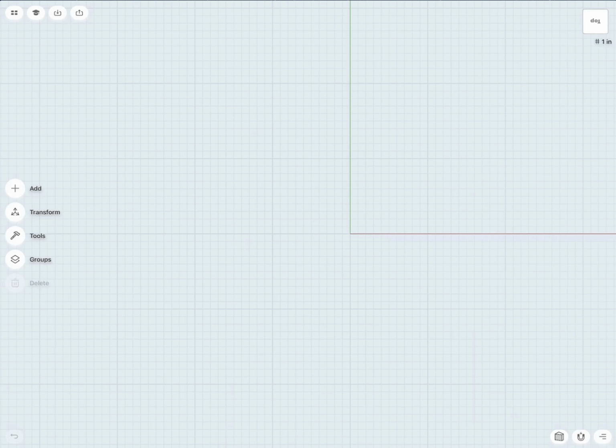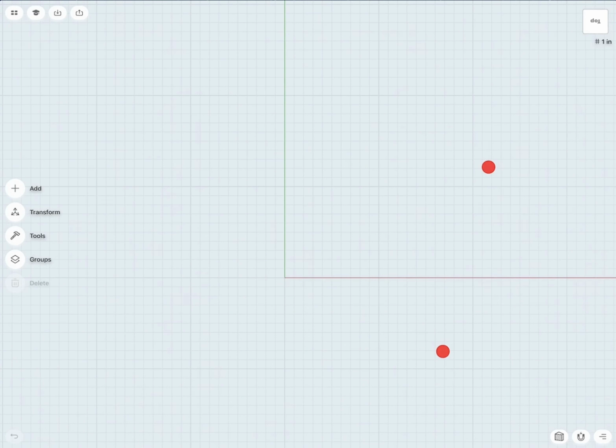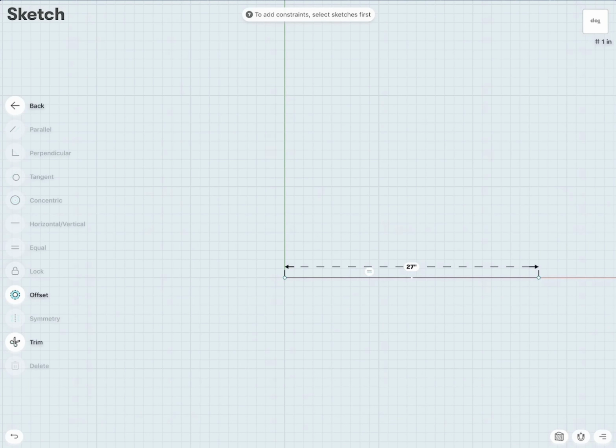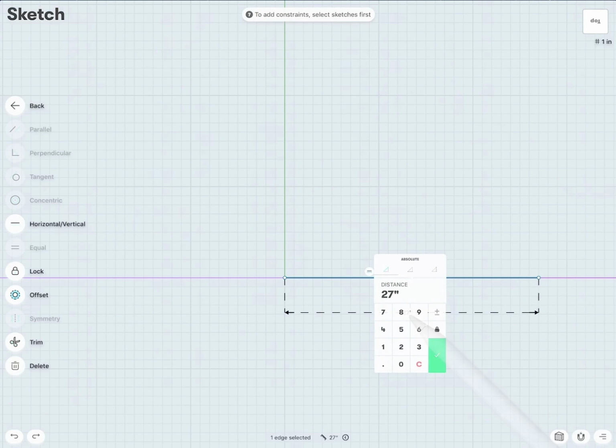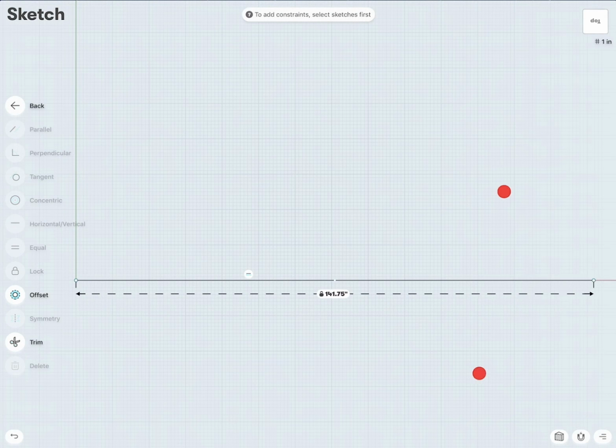Now, architectural drafting in Shaper works a little bit different than in traditional architecture modeling programs. And the main difference is here how we, for example, rotate and position everything. So the room I have is 142 inches wide. So somewhere I could make a line. You see, when drawing this line, I get the dimension readout. So I don't have to draw the line exactly to the length I need. I can just draw a short line, then with the pencil tap on the distance and then type in 141.75. And because we work with inches, that's going to be 141.75 inches. Very good.